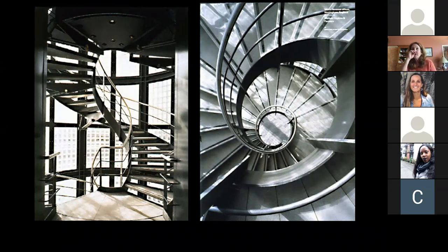Okay, and I saw some earlier questions about roof ponds in hot, dry climates. Now, one of the reasons they work in hot, dry climates is because they're radiating to the night sky. What happens in a humid climate? You have a lot of cloud cover, you have a lot of moisture molecules in the sky, and so you're going to not have exposure to those cold temperatures as much.